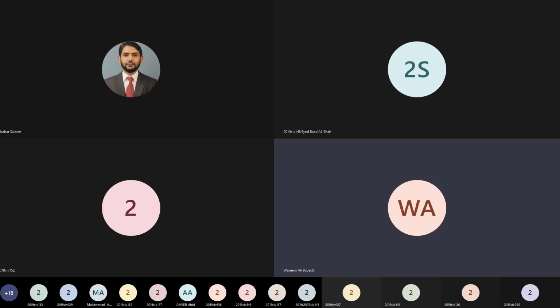How did we get our main scale reading? In our chat box, you can see that I have written the measurement. The first value is 1.2. How did we get that? We move in the counterclockwise direction on the large scale, and every small division is equal to 0.2 millimeters. So 0.2, 0.4, 0.6, 0.8, 1, and then 1.2. The needle is ahead of 1.2.